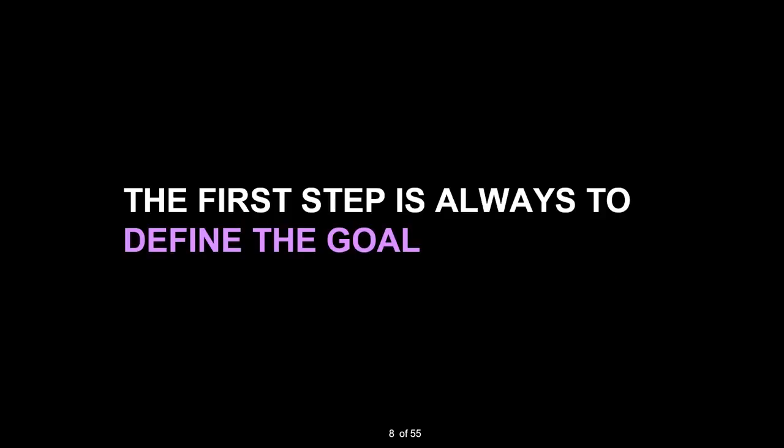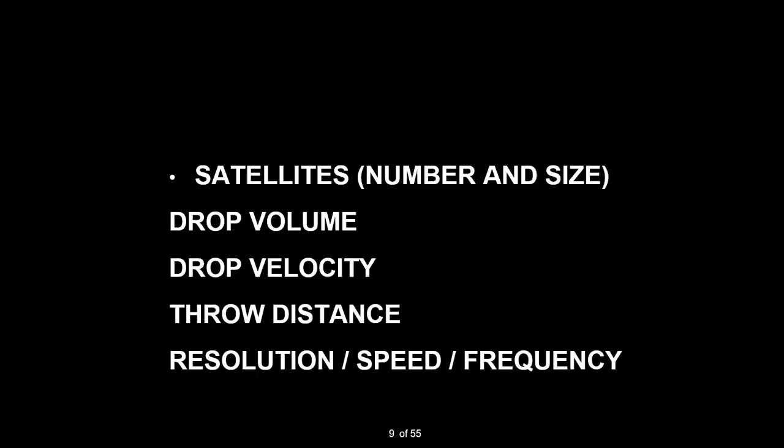So the first step in waveform optimization is to define the goal of what isn't acceptable, such as satellites, and if there are, how big and how many is acceptable for your application. The volume of the main drop, the velocity of that main drop, how far you're going to be spacing your print head and your substrate and how far that drop needs to travel, and then the resolution, speed, and jetting frequency. All of these things are important to know before you start optimizing your waveform so that you know what you're trying to accomplish.